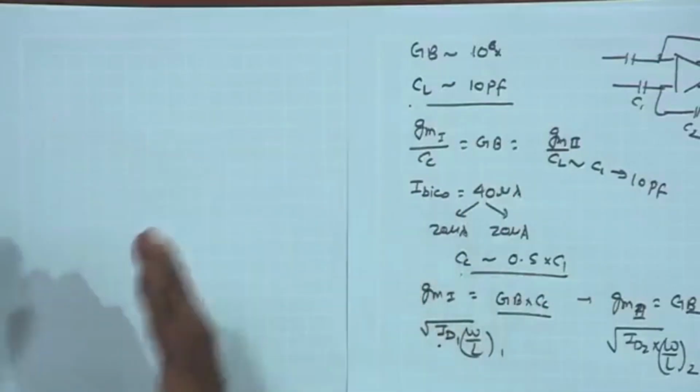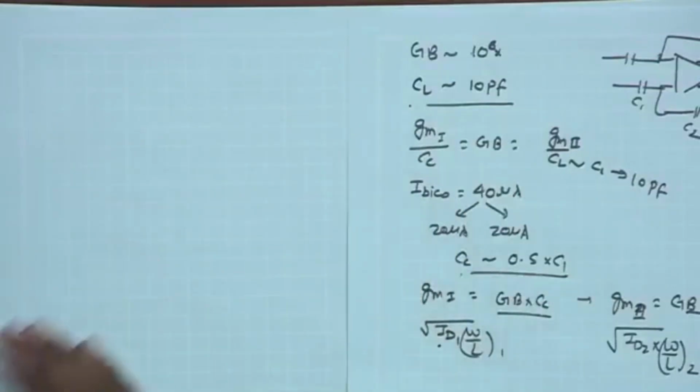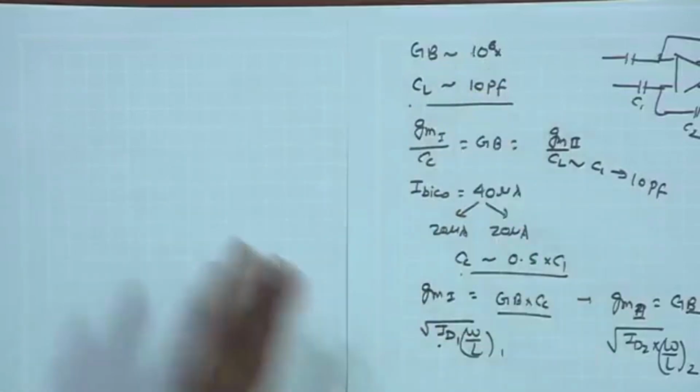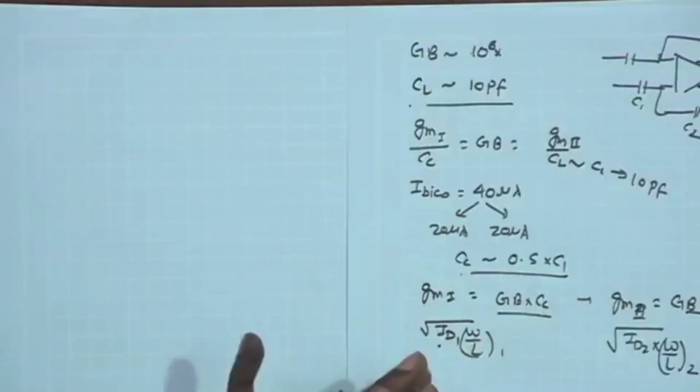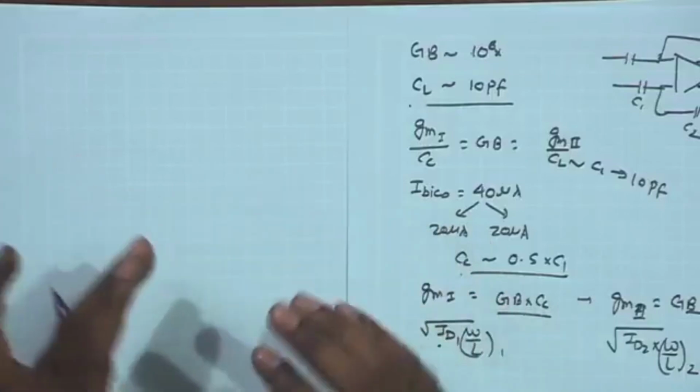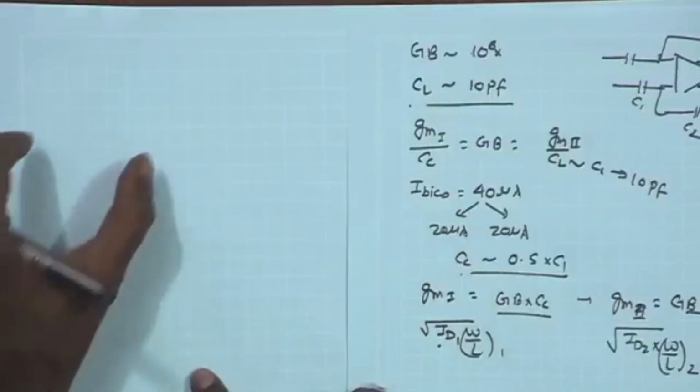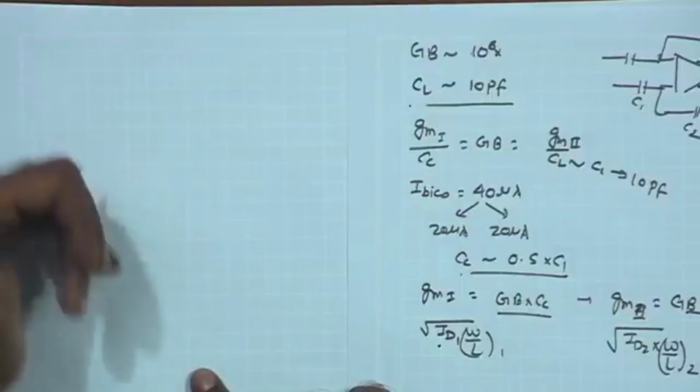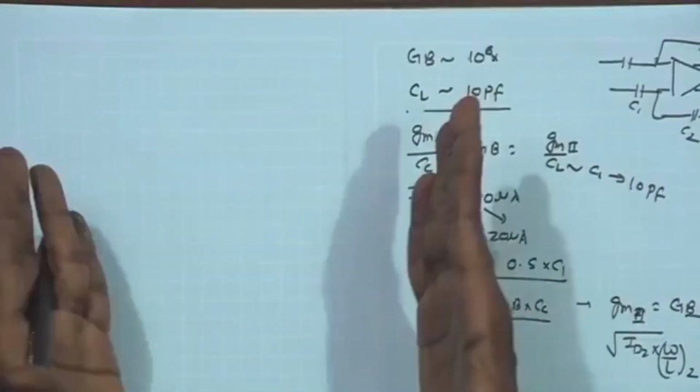We can take a smaller fraction of the gain for the first stage and a larger one for the second stage, or vice versa, and that also depends upon design considerations. If you are going for a larger gain for the first stage, once again it contradicts with the noise requirements. So, for the time being, let us bifurcate the gain requirement equally.